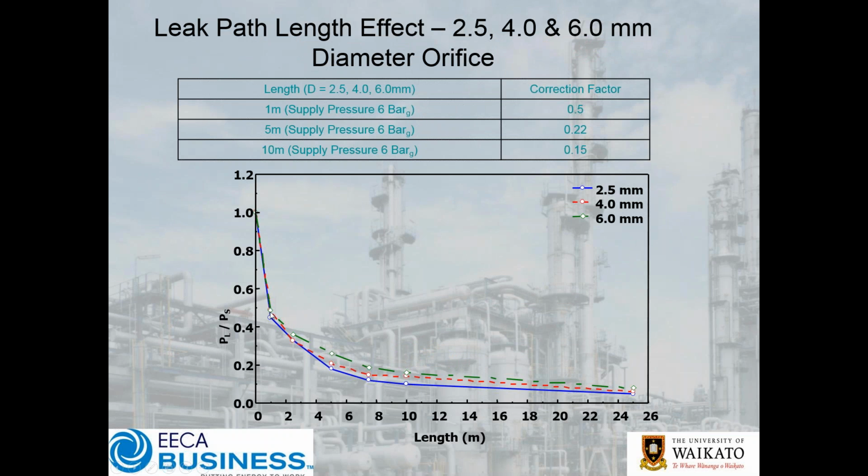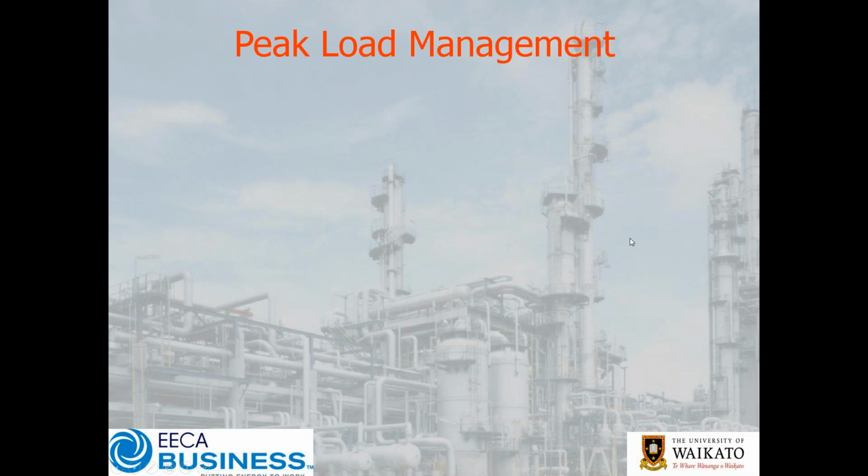Okay, and then as we extend the length of our tube, that rate drops off immensely, and it's not uncommon to be in the 20 to 15% range. And so what started out as being an assumed 100 CFM loss very quickly becomes sort of a 10 CFM loss or less. So it's very important that we don't overestimate and get carried away. They're still worth fixing, just not a $12,000 to $15,000 fix. It becomes a $1,000 to $2,000 fix instead. Still worth doing in most instances.